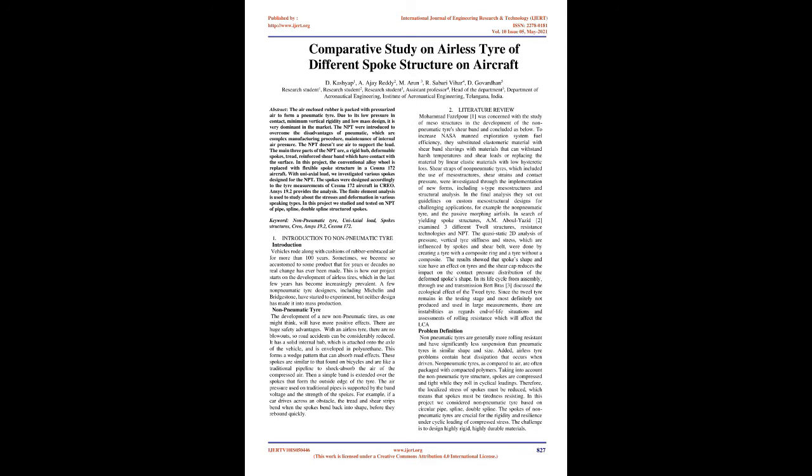The spokes were designed according to the tire measurements of the Cessna 172 aircraft in CREO. Ansys 19.2 provides the analysis. The finite element analysis is used to study the stresses and deformation in various spoke types. In this project we studied and tested NPT of pipe, spline, and double spline structured spokes.